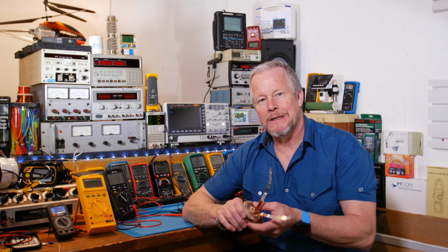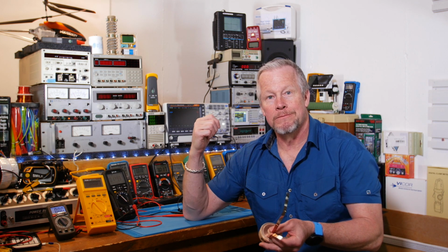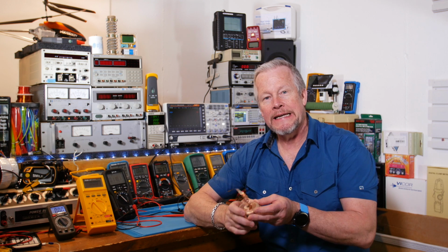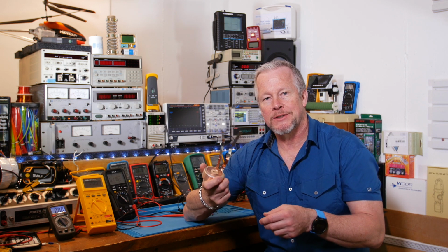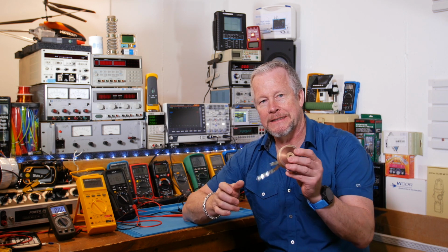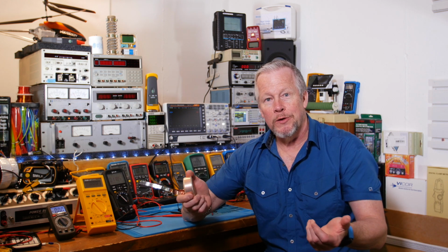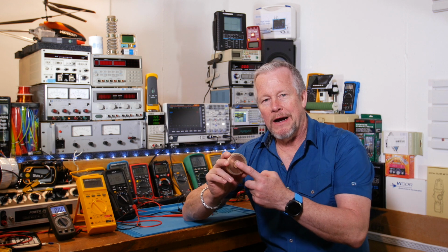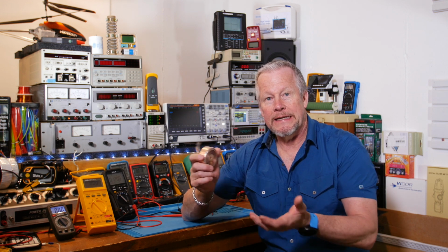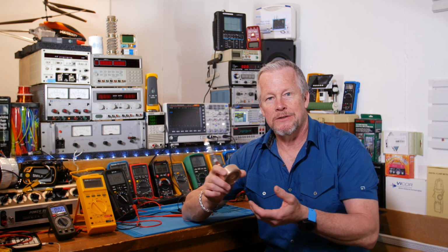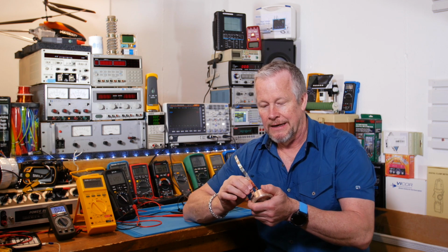Today what I want to do is show you how to use a scope that can do Bode plots, how easy it is to do the impedance curve of, say, an inductor in this case. Resistor, capacitor. You might have some parts around and you don't know the value, or maybe they have iron cores, ferrite cores, and they can change over frequency. You just want to check it out and see what the impedance is over frequency.